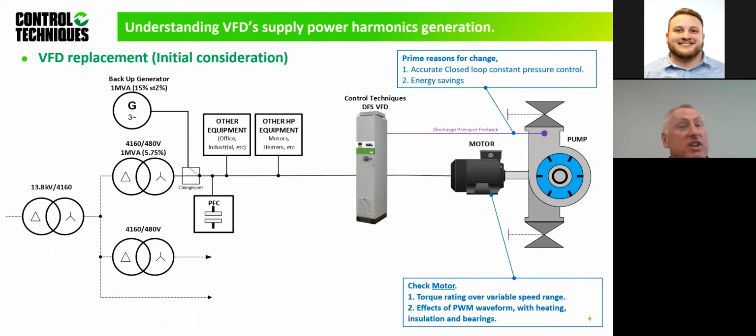You may switch out the motor because now we've got to have a variable speed range, of course, and also be able to cater with the PWM switching waveform with the dV/dt. So it's important that these existing motors, can they do them? Maybe if they're well oversized, they could, but usually they get changed out with the drive.